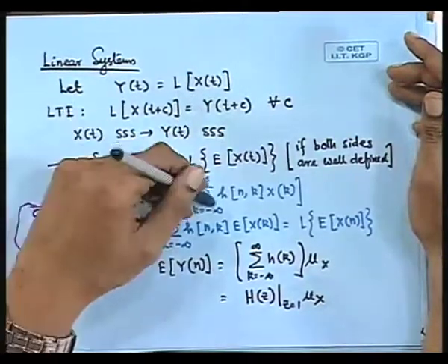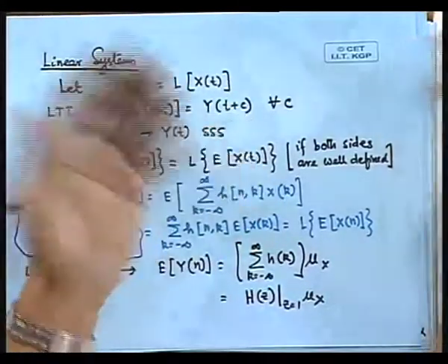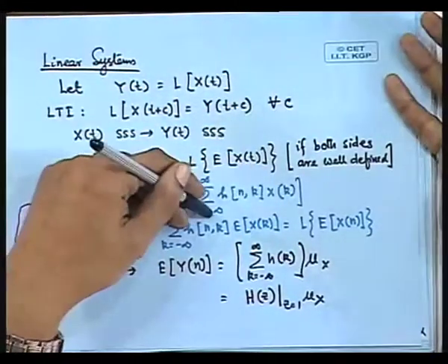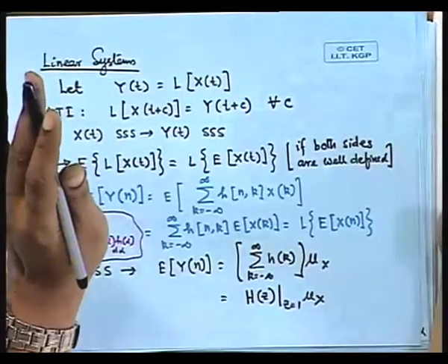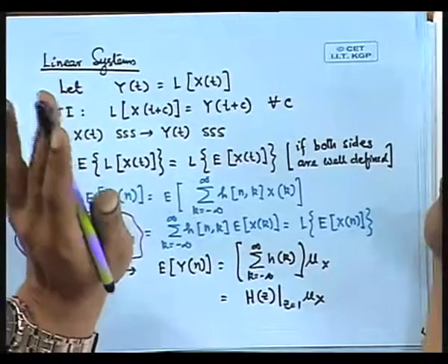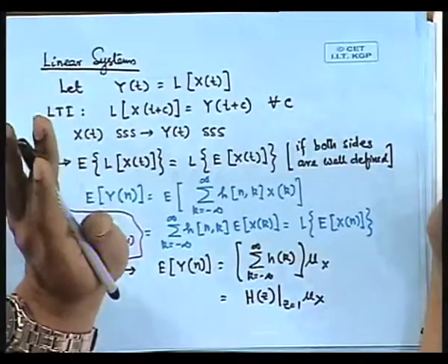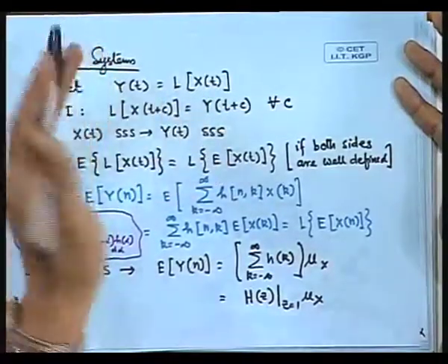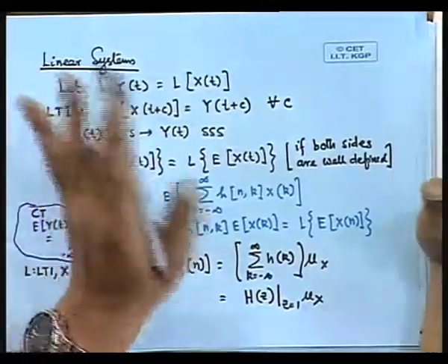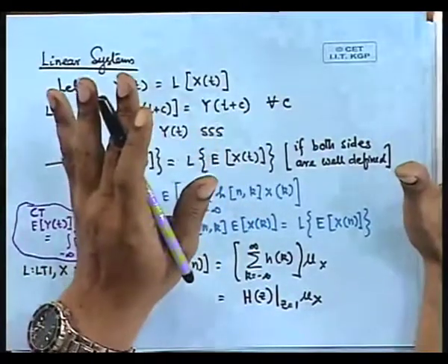So what you are going to do is sum this x_k every time. Now x_k is non-zero and you are summing it over an infinite number of terms, so that limit will not exist at all, right. Such complexities may exist, but for the time being we'll keep our eyes shut on that and only talk about BIBO stable systems for which the impulse response sequence will be convergent, that is, a result for which this sum will actually converge. So we will only talk about those systems for the time being.